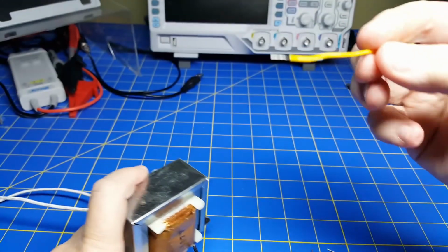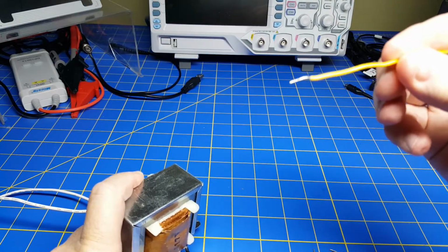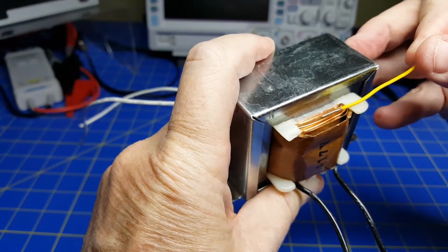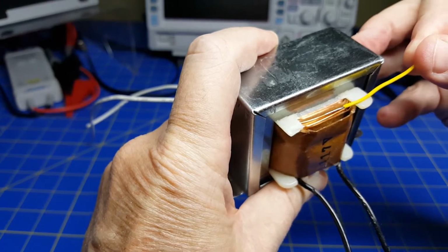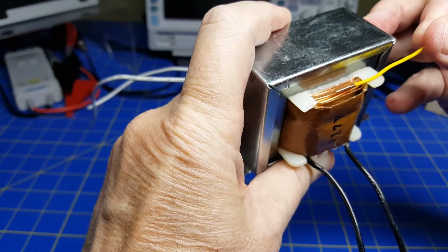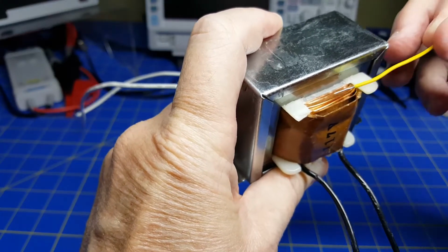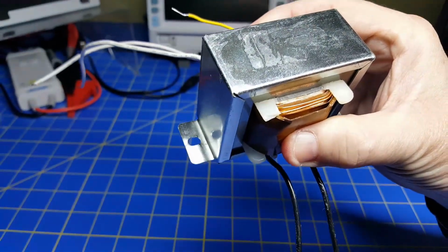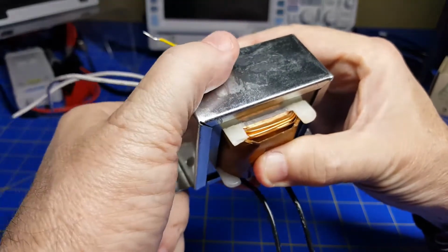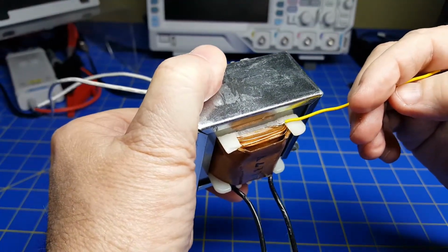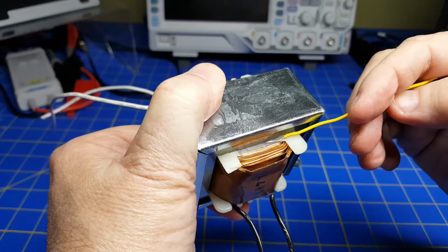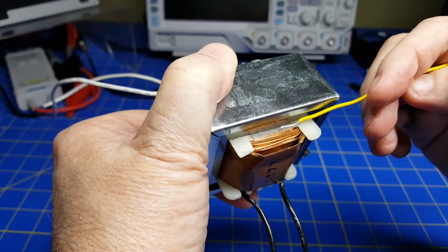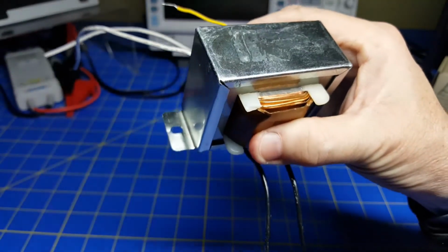Now, I've got here a piece of number 22 gauge wire. So if I hold that up to this 12 volt winding, you can see, yeah, that's about the same size, right? Maybe not exact, but at least it's about the same size. So we can start out knowing that this 12 volt winding is probably in the order of 22 gauge wire, all right? And then if you look on the inside, you can see, well, that's a lot smaller. So maybe that's 30 gauge or something like that. So that will be helpful because it will help us kind of figure out things like resistance.